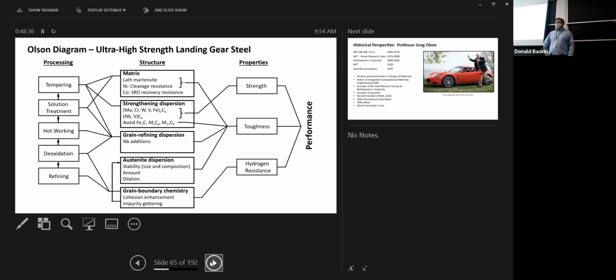This is, I can tell you, like in the wind turbine industry, a lot of these wind turbines that are out to sea, like in the North Atlantic or the Baltic Sea, north of Europe, between mainland Europe and Sweden and so forth. There's a lot of wind turbines in those areas, and it gets to be really low temperatures. One way they strengthen these materials is by specifying niobium in there. Not a lot, only a fraction of a weight percent, but it's enough to refine the microstructure enough to get an increase in strength.